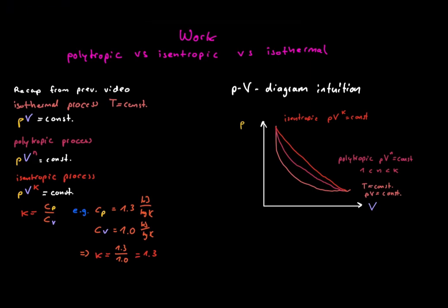First, isothermal compression. Isothermal means constant temperature. The process follows P times V equals constant. During compression, heat leaves the gas, so the temperature stays constant. Second, polytropic compression. A polytropic process follows P times V to the power N equals constant. This describes real compression between idealized cases.